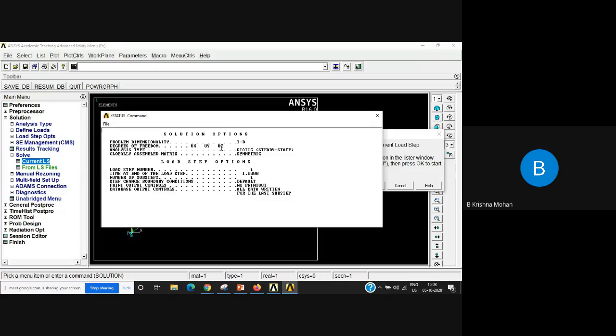You don't have rotations. If you pick a beam element, then the beam element has 6 degrees of freedom, that is translation along XYZ and rotation along XYZ. Since a truss member behaves like a bar, it will have only translations along XYZ because it is considered as 3D. That's why each node has 3 degrees of freedom.